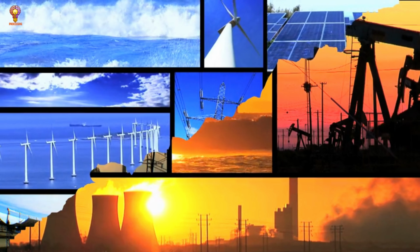3. Hydroelectric power plants. Hydropower plants generate electricity using the kinetic energy of flowing water. Step-by-step process. Water flow control: water from a dam or river is stored and released through penstocks, large pipes. Turbine rotation: the fast-moving water hits turbine blades, making them spin. The turbine is connected to a generator, converting mechanical energy into electrical energy. Electricity transmission: the generated electricity is sent to transformers for distribution. Water recycling: the water is released back into the river with minimal environmental impact.